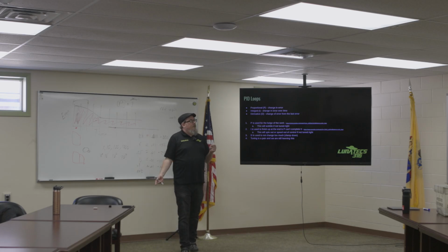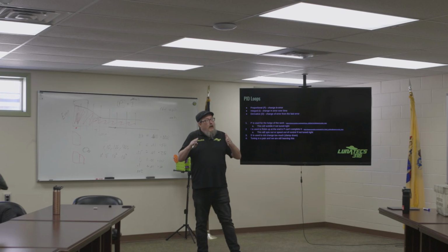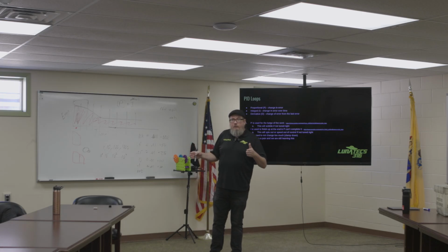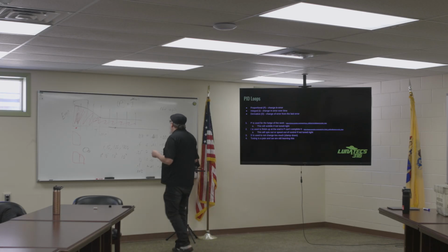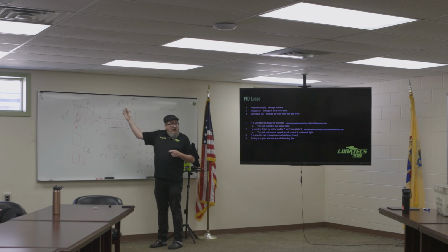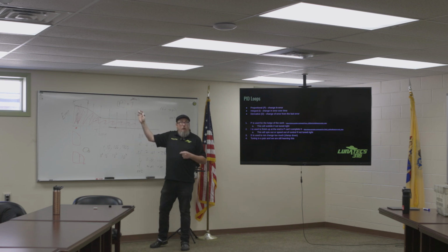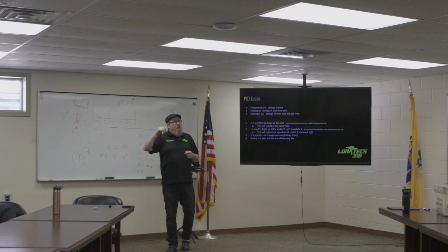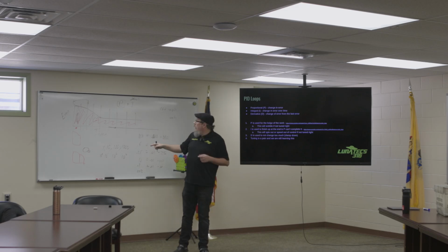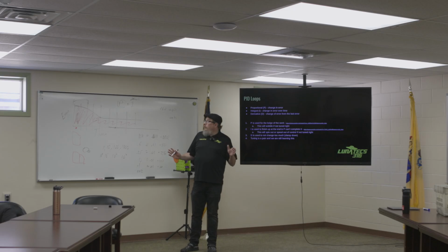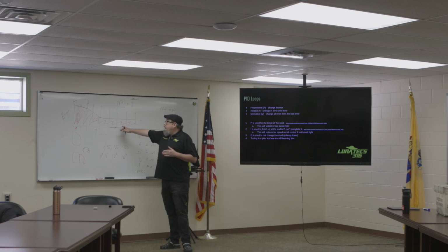Those are orders of magnitude. They're 10 times greater than the previous one. So usually when we're using integral, the I in the PID loop, we will make it 100 times less than the value of our proportional, because this too is going to add power.